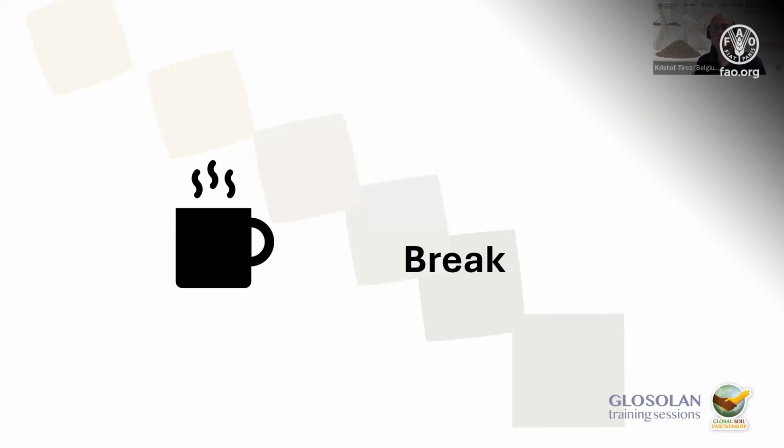Yeah, I see already one question, Ingeborg. Are there any models to model lateral movement of pollutants? There are. Usually in the upper soil, in the unsaturated zone, the movement is downwards. So it's very typical to just have 1D vertical movement. But like the Hydrus 1D, you can assume any direction.